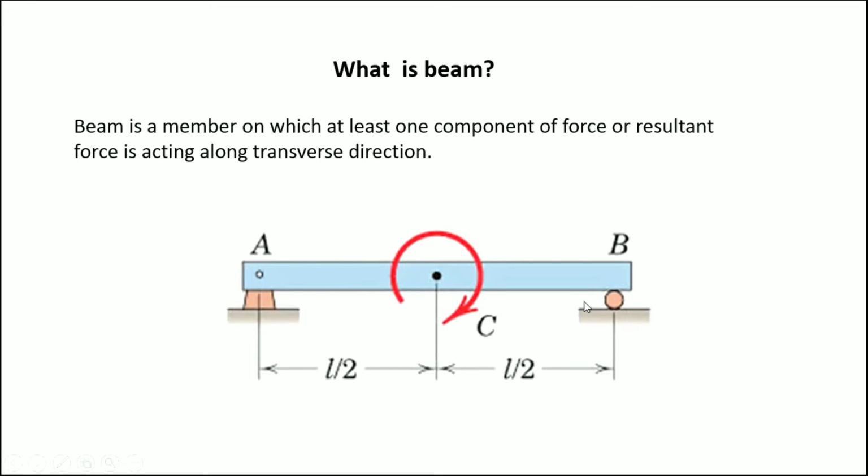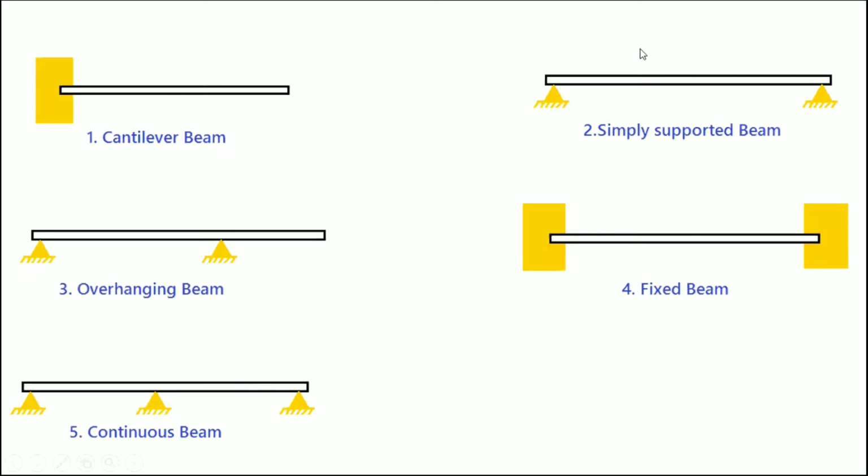It is also called simply supported no matter whether both the supports are hinge supports, or both the supports are roller supports, or either one support is a roller and the other is a hinge. That means if here is a hinge instead of this roller, then we can still call it a simply supported beam. Got it?